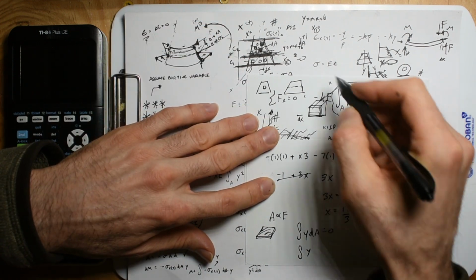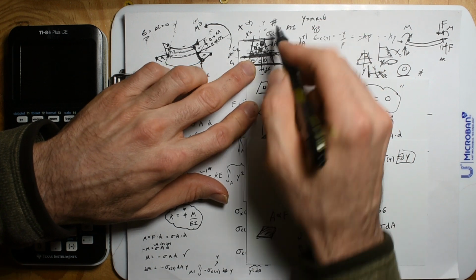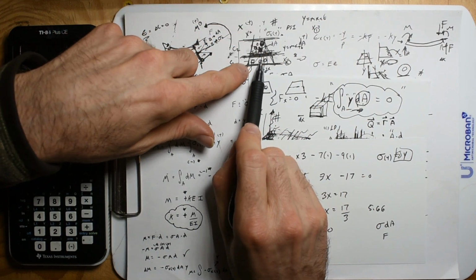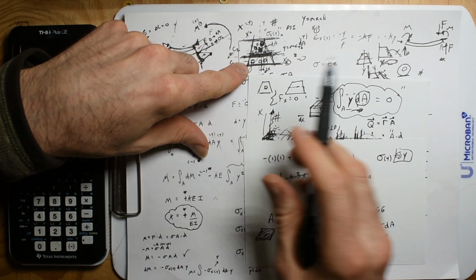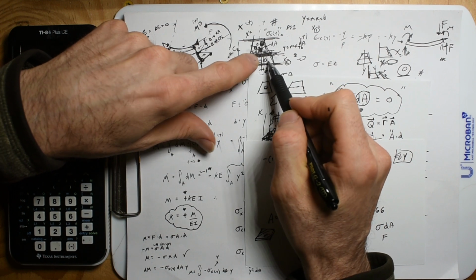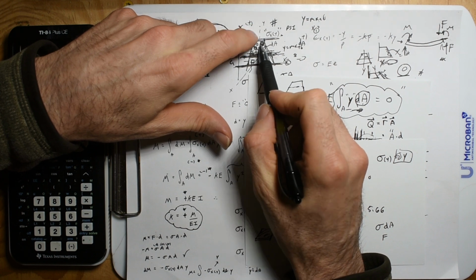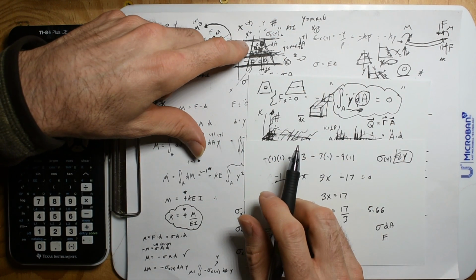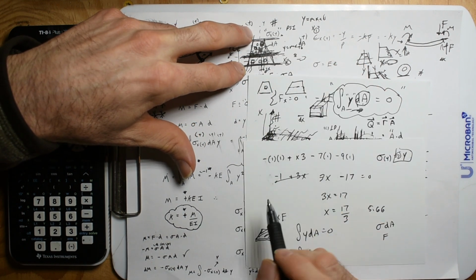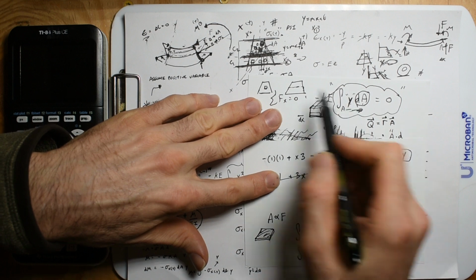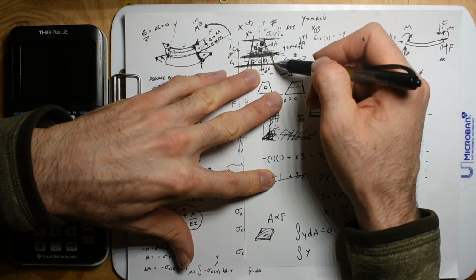It says if we have an axis that we chose, and we take that area and multiply it by the distance away, and do the same for the area that's below the neutral axis, which will have negative, it's the leverage of that area times its distance, so it's the moment of that area summed, and the negative moments and positive moments are going to cancel, and that point is going to be the neutral axis. So it says if we're on the neutral axis, the moments of those areas will be zero.